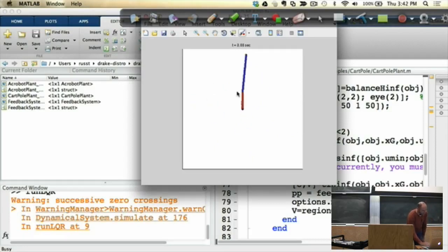It was outside the region where the linearization worked, but actually pretty big perturbations, if you bang on the Acrobot, and it's again only applying a torque at the elbow, but it's using the inertial coupling between those 2 degrees of freedom to stabilize the origin at the top.